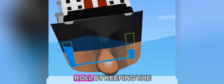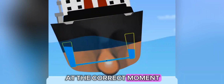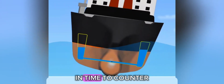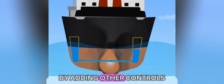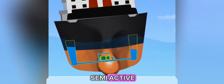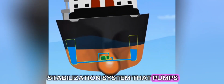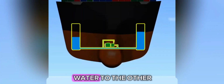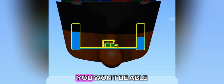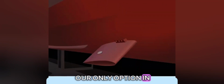One can counter the roll by keeping the fluid in place while the wave crests, and then releasing it at the correct moment to allow it to flow to the other side in time to counter the next wave as it arrives. By adding other controls, one can make them semi-active or even fully active by adding a gyroscopic stabilization system that pumps water across whenever needed. As the pumping of water to the other side is time-consuming, you won't be able to accomplish immediate stabilization. The fin stabilizer is our only option in that case.